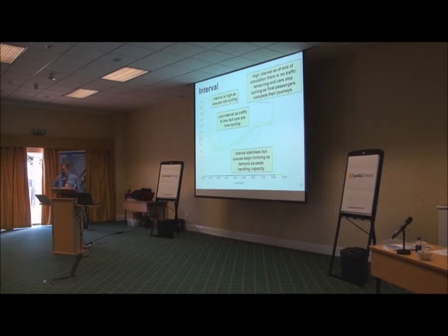So let's have a look at the individual characteristics and what's happening where. At the beginning, when you've got hardly any traffic, most of the lifts are just doing nothing. So if you define interval as the time between departures from the main terminal floor, then if there's no traffic, the interval becomes infinite. So we've got a high interval because nothing's happening.